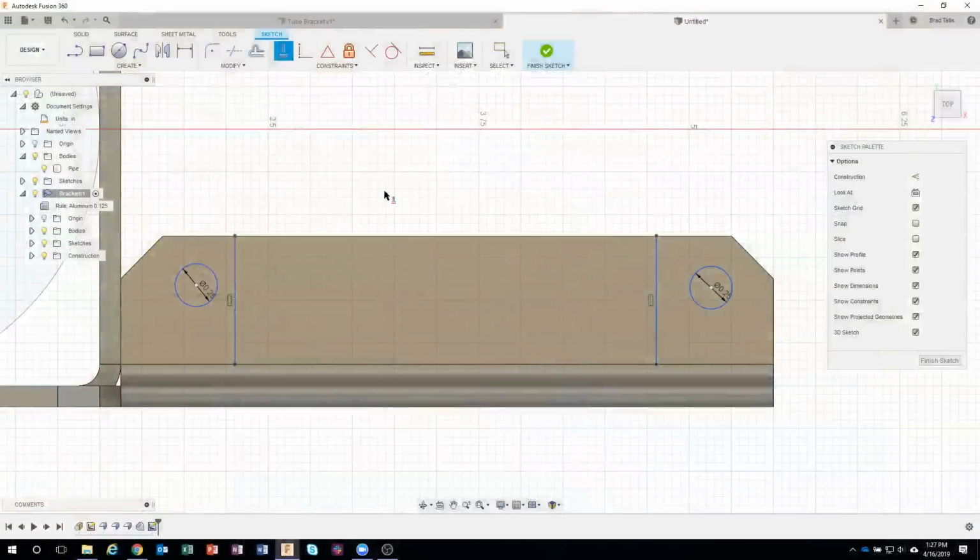Well, the fact that it was kind of sliding along that line, even though it might have said 90.0, it might have been 90.005 or something like that. Whereas by using a constraint, we are physically saying that has to stay straight up and down. So I like to let the software do the hard work, and down the road, if I got a weird result, it might have been because I didn't force that to be straight up and down.